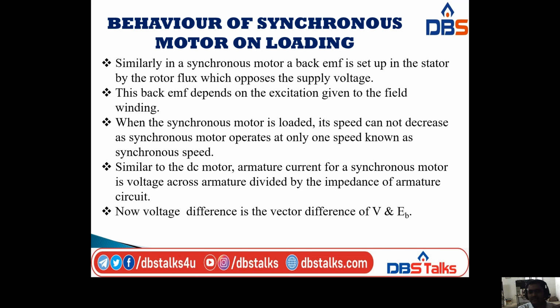But in the DC motor, when the load increases, what will happen? The speed will decrease automatically. But in the synchronous motor, there is no change in the speed. It always rotates at a constant speed, that is the synchronous speed. There is no change in the speed after increasing or decreasing the load. That's why I am taking this point.